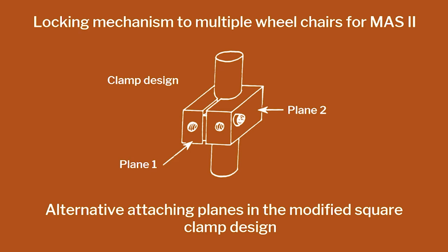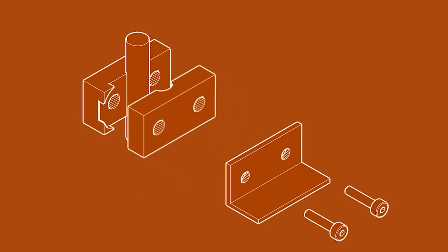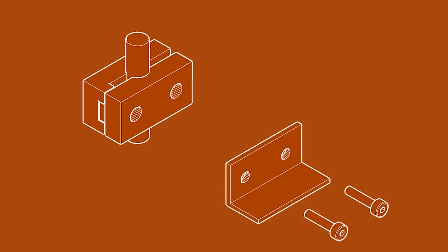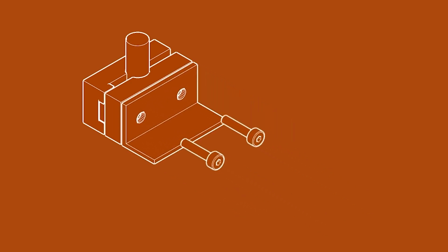I can put the screws on this side, and therefore those screws can do double functions. One is they can attach to the bracket, and two, they can clamp the mechanism. So in other words, my number of parts goes down. Good news. So this becomes your design. So you have this plane where the bracket is fixed, these two screws with which it is tightened, and both these screws are Allen screws, let's say, which means that it has a hexagonal head in the middle. So I can then operate with a single tool, which is good, rather than multiple tools, because then my cost of tooling is less, my cost of training somebody to use the tool is less.